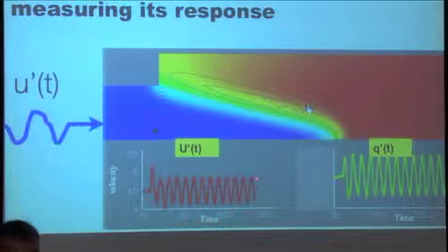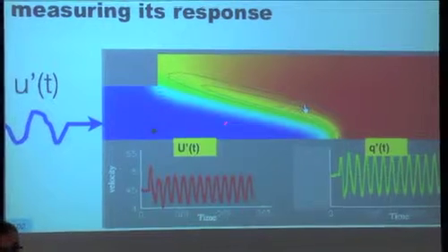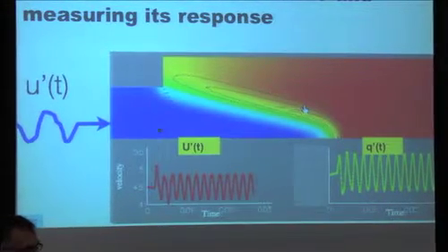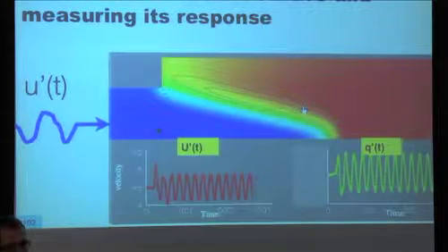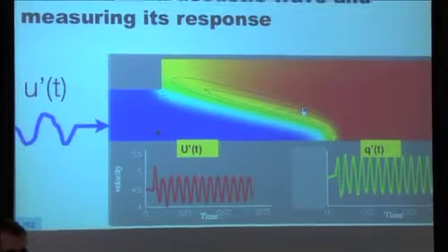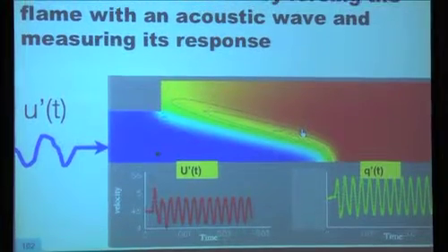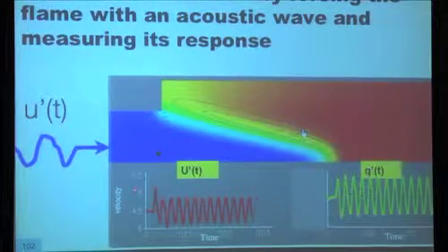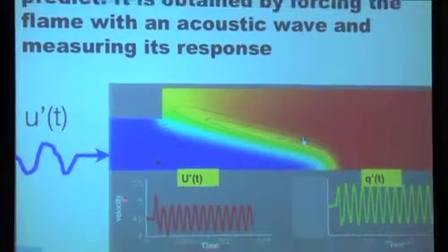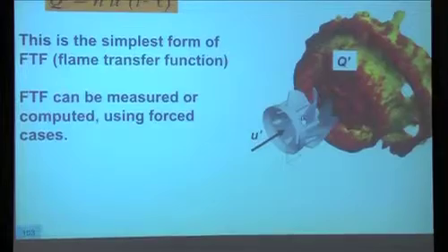You can do it in an experiment. In an experiment, you put a hot wire here, you put a photomultiplier here, which measures the whole flame. You plot the two curves, you look at the delay, and you have it. Okay? And to find the interaction index N, you normalize signals, and you can find it in the same way. So in principle, it's quite easy to do it. In practice, you're going to see, like always, it's not that simple.